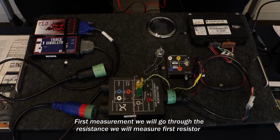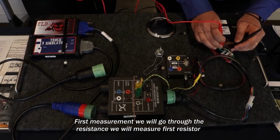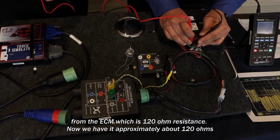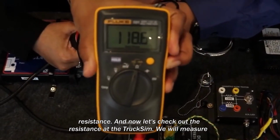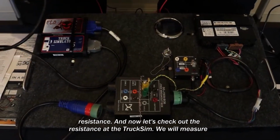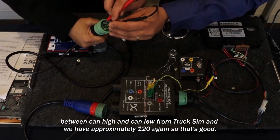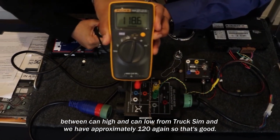First measurement, we will go through the resistance. We will measure the first resistor from the ECM, which is 120 ohm. Now we have approximately 120 ohms resistance. Then let's check the resistance at the truck sim. We will measure between CAN high and CAN low from the truck sim, and we have approximately 120 again, so that's good.